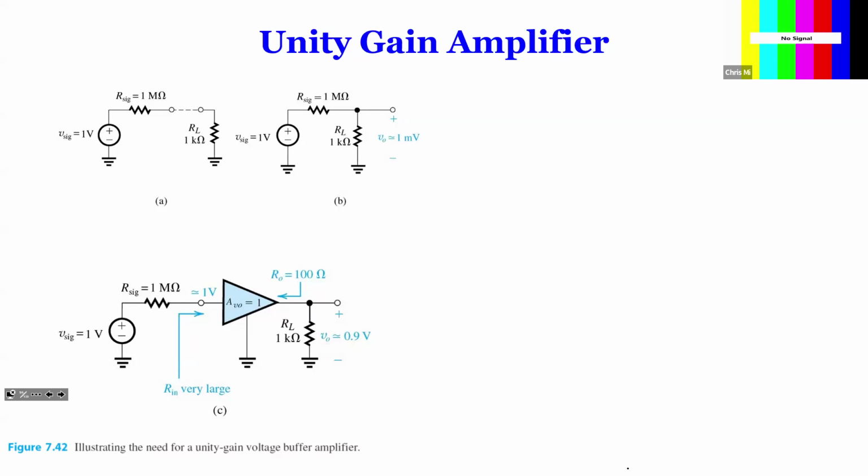It's often the case that you have one unit gain amplifier at the input side and a unit gain amplifier at the output side. And in the middle, you have a regular amplifier to give you a lot of gain. Okay, I have the unit amplifier coming in, 1 volt, and the output is 1 volt, but in the middle I have very large gain, maybe say 5,000. Then I have another stage that is a unity gain amplifier because I decrease my output resistance. So that's how this works.